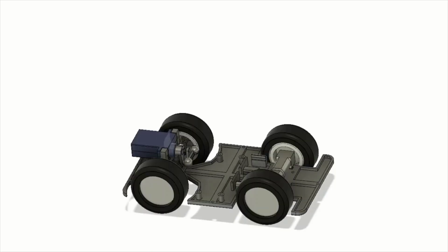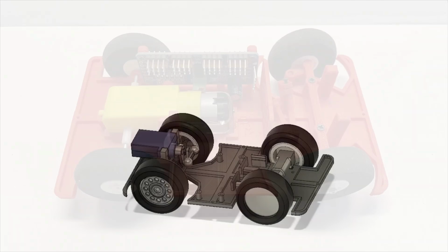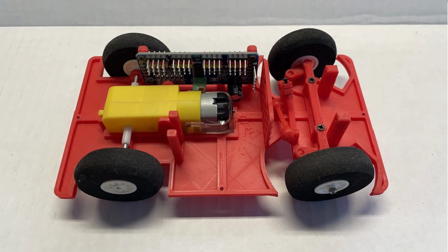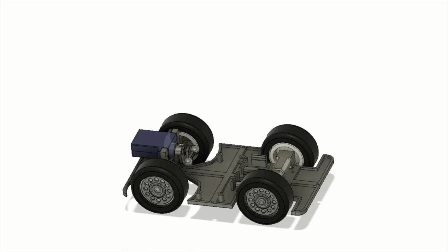As for the rear wheels, they are powered by 2 motors. Initially I attempted to use one motor with the gear connected to a fixed shaft for both wheels, but this setup didn't work well. Then I switched to using geared N20 motors, and 2 of them fit perfectly. This arrangement eliminates the need for a differential gear, as it can be achieved electronically. Each motor gets its own H-bridge to control them individually.